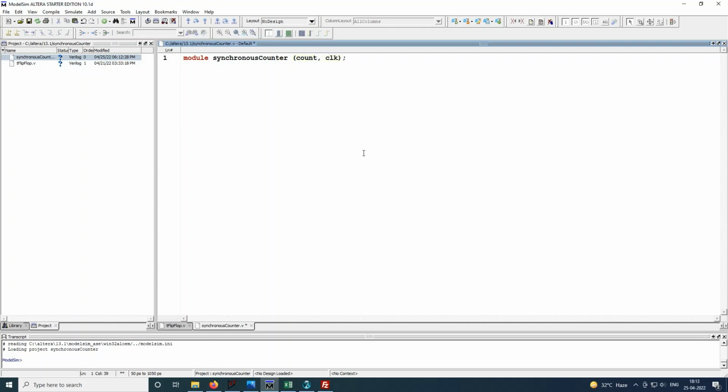Now I've already done the design steps wherein we need to construct the state table having the present state and the next state, and solve using the excitation table for whatever will be the values of T. So essentially here we will again need 3 T flip-flops, and we have to essentially calculate what will be the T input.